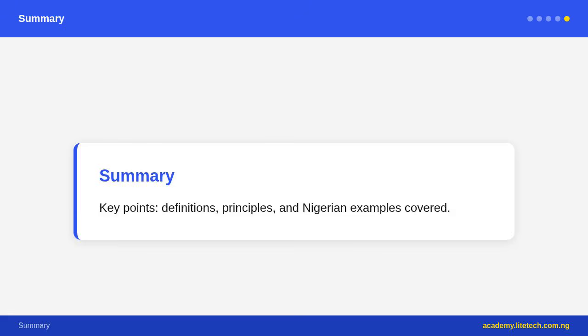Today we covered that a microphone converts acoustic energy to electrical energy. Two main types: dynamic microphones, robust, no power needed, handle high levels, and condenser microphones, more sensitive and detailed, require phantom power. Polar patterns describe directional sensitivity, cardioid most common, omnidirectional captures all directions, bidirectional captures front and rear.